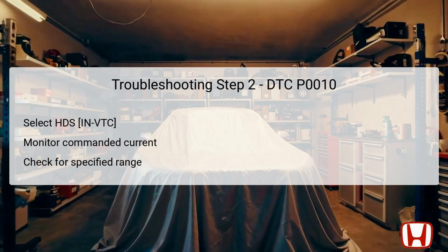Establishing whether the command and actual currents are aligned will help narrow down whether the issue is with the solenoid itself or if wiring and connections need further investigation.